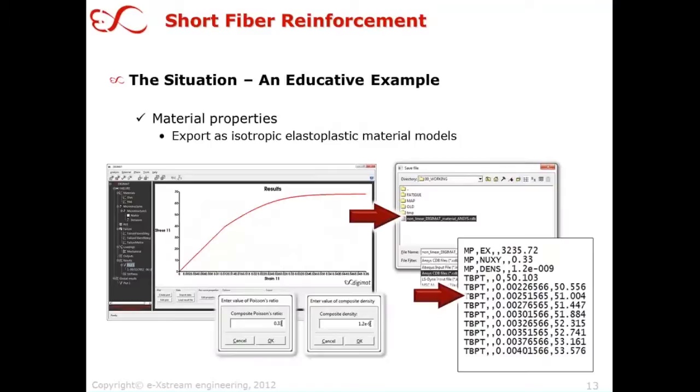So this we use, and then for the material properties we use some nice feature which you can find in the DIGIMAT MF module. It's that you predict, really based on some microscopic material model, a nonlinear stress strain curve, and then if you have one curve, you can export this curve into some material card which is isotropic and ready to use with any FEA solver. So basically what we did here is that we fixed the underlying microstructure in the same material, and for this fixed microstructure, we exported material properties.